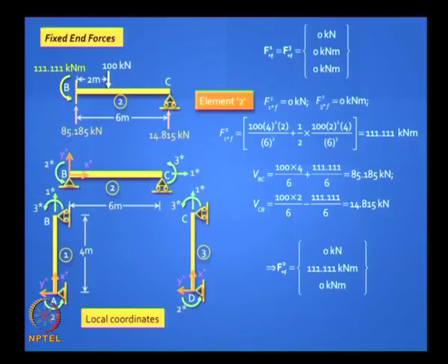You have only one moment there, because here you are accounting for the fact that at C there is a hinge, so you do not get it. So does it make sense now? I have taken care of the hinge, but I am still keeping my full fledged 3 degree of freedom matrix, but I will take advantage in the next situation.